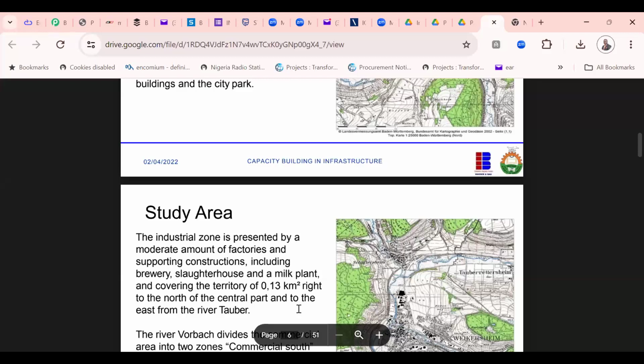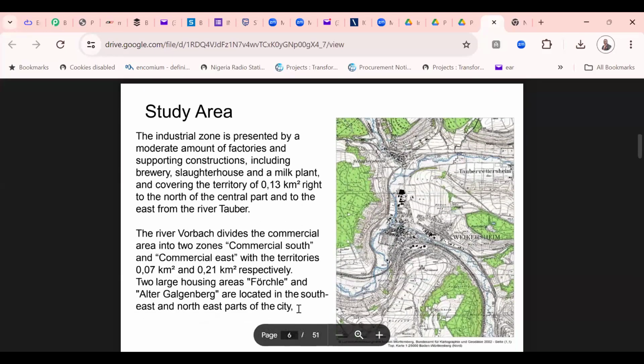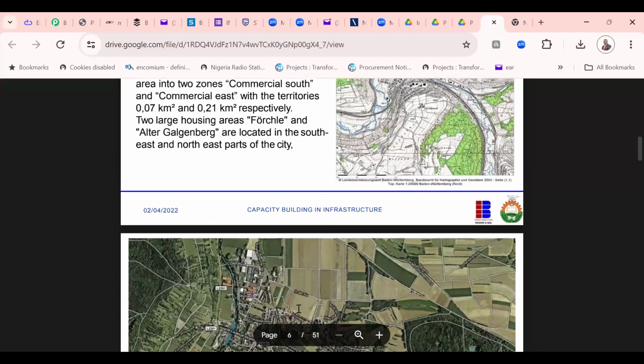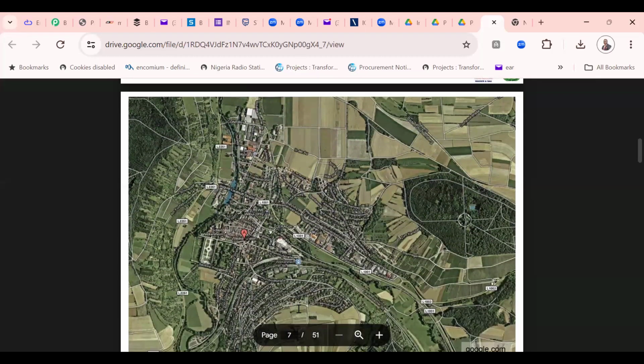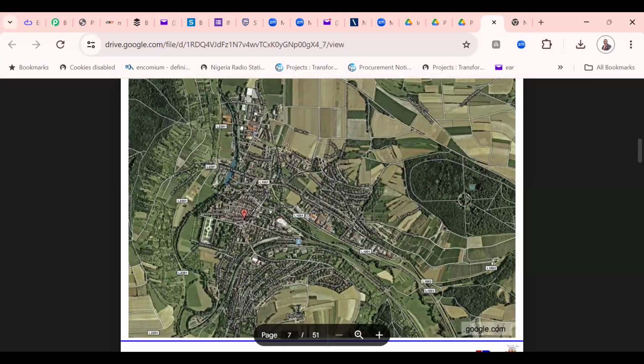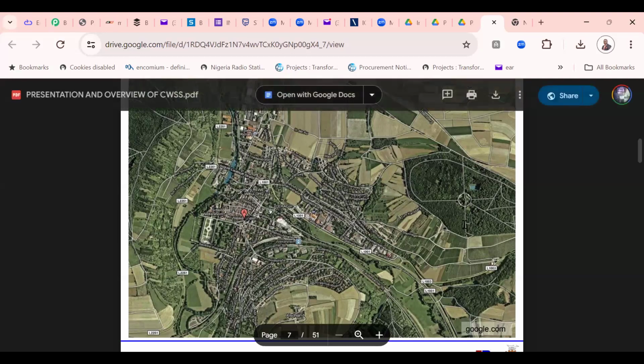You describe how you're going to source the water, how each source is going to contribute, how you're going to take some from surface water, how you're going to take some from groundwater, why groundwater is possible, why it's not potable, why you need a treatment plant there, or why you don't need a treatment plant, why one market close by should be relocated so it doesn't contaminate the water source, why farmers should move away, why there should be a buffer around the water area. Like this place on my screen, you can see that this is like a buffer.